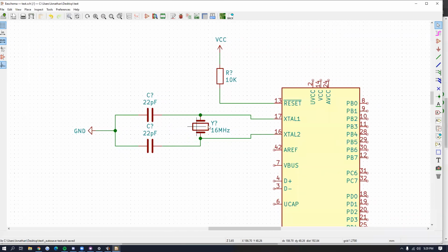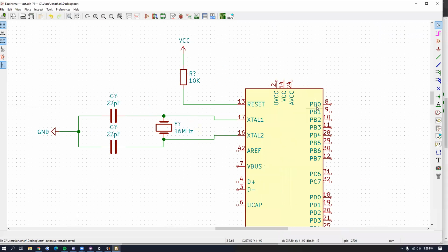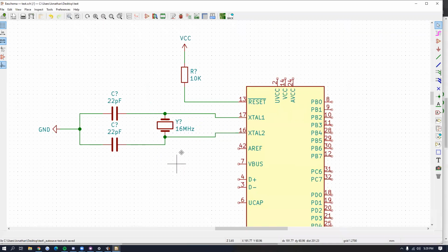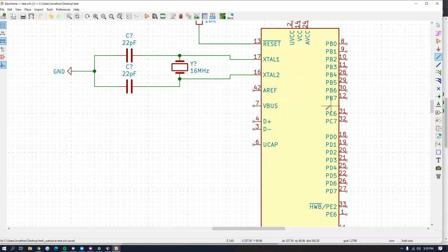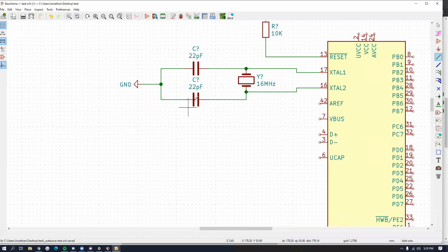All right, so we got the crystal down, got this down. Let's see. All right, we can start. Okay, so on the reference, there's supposed to be a 0.1 microfarad capacitor. So let's add that here. We'll get another capacitor. I'll just copy it from here by pressing C, so it's easier. I'll put it here, and I'll draw the wire connecting it like this.